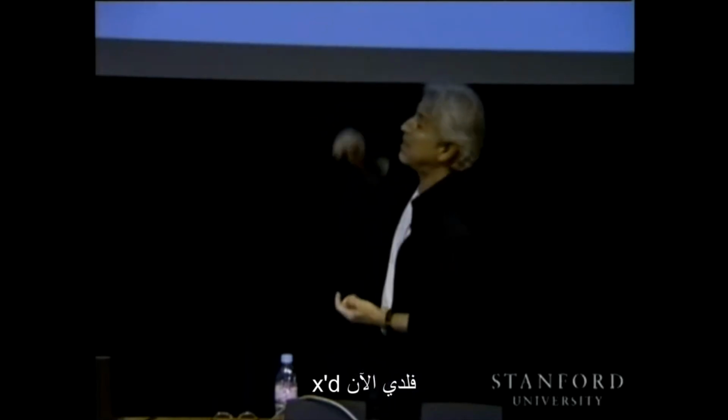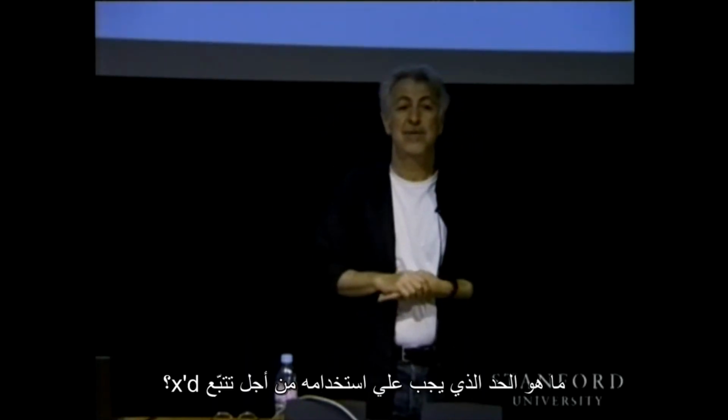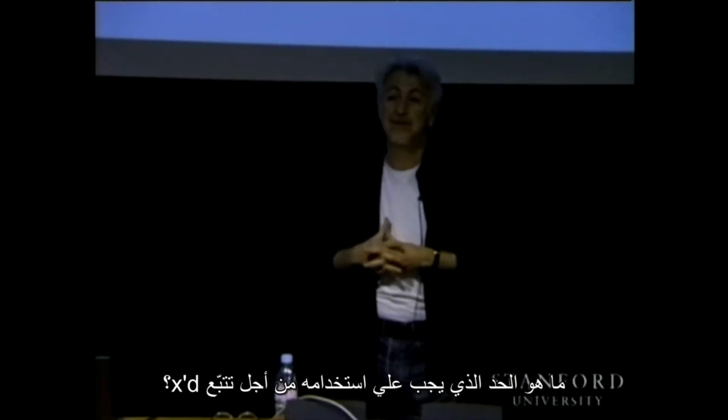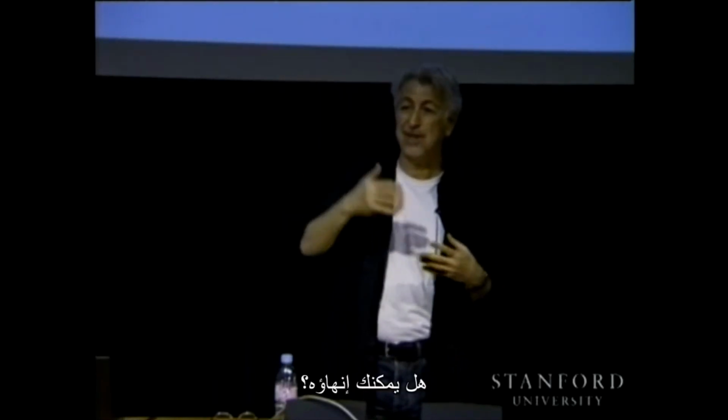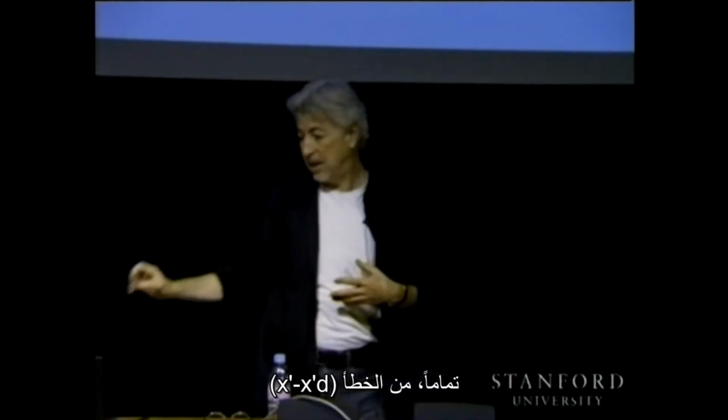Because now I have x dot desired. What would be the term that I should use to follow x dot desired? So that would be minus kv, x dot minus x desired dot. Exactly. I form the error x dot minus x dot desired.